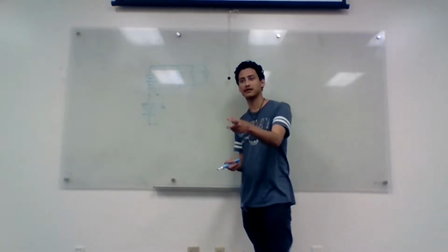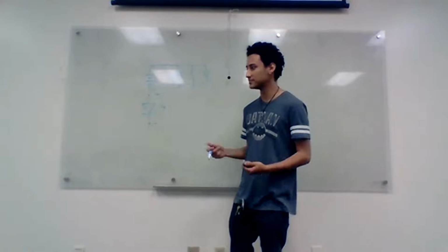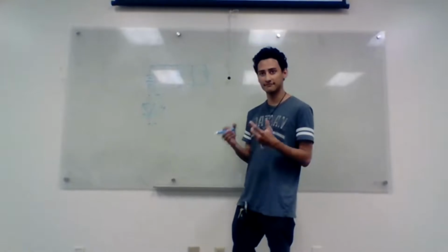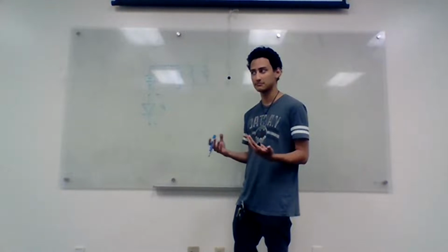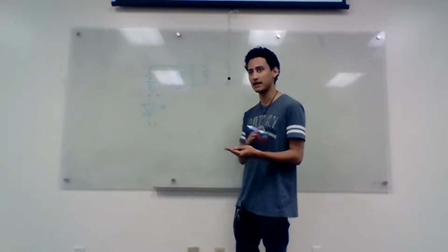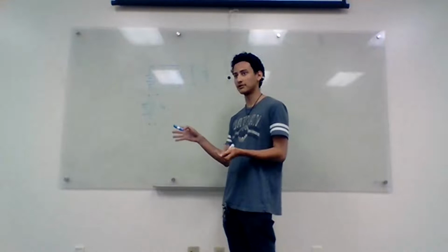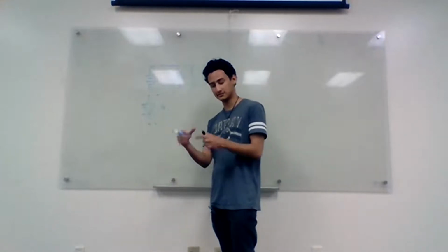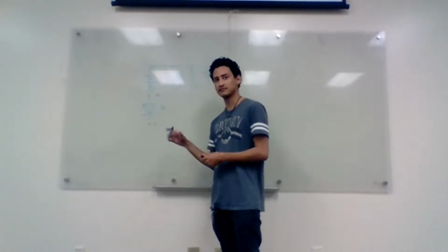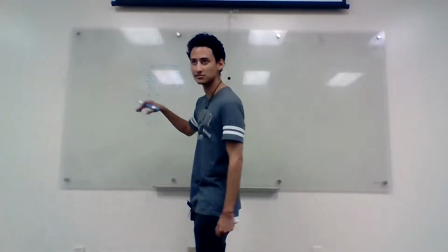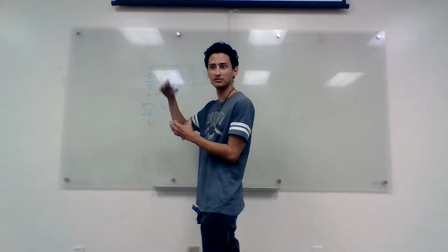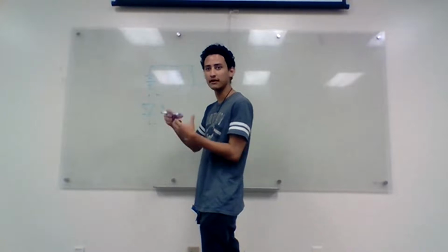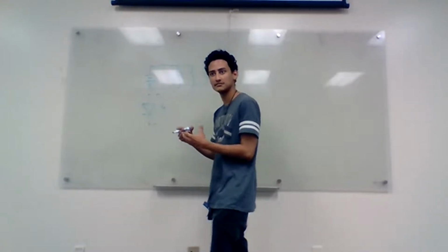Mathematical, right. G sub D and C sub D are not physical things, they are ways to describe a phenomenon. So it's the way that you describe how much forward transconductance you have. That's G sub D. And then C sub D is describing some stuff that's happening related to the way charges move. But they're not physical capacitance.